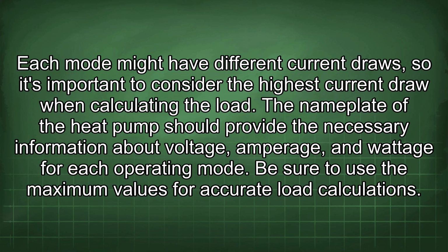Each mode might have different current draws, so it's important to consider the highest current draw when calculating the load. The nameplate of the heat pump should provide the necessary information about voltage, amperage, and wattage for each operating mode. Be sure to use the maximum values for accurate load calculations.